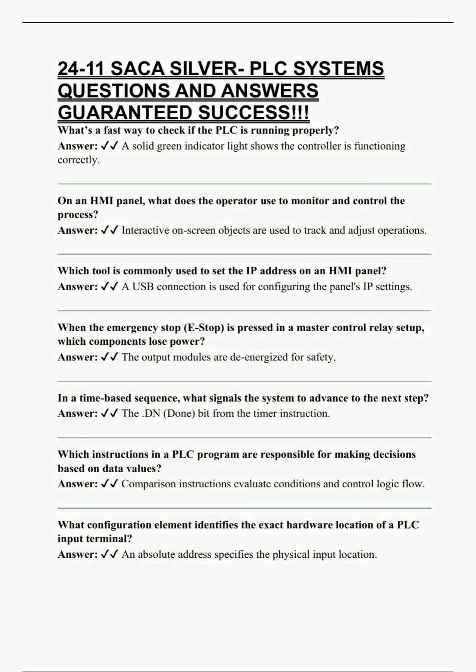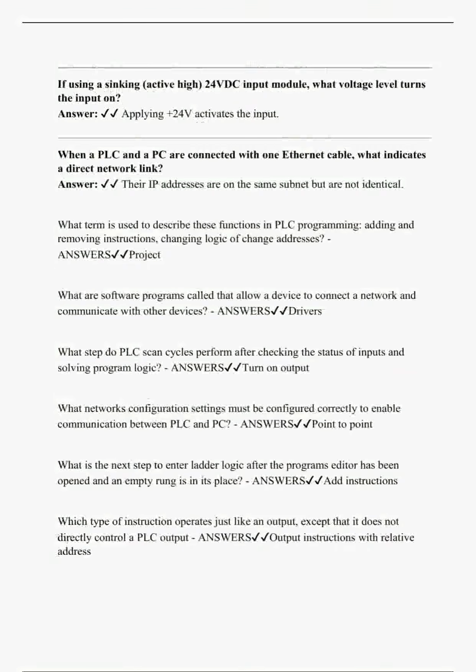What configuration element identifies the exact hardware location of a PLC input terminal? Answer: an absolute address specifies the physical input location. If using a sinking active-high 24 VDC input module, what voltage level turns the input on? Answer: applying plus 24V activates the input.